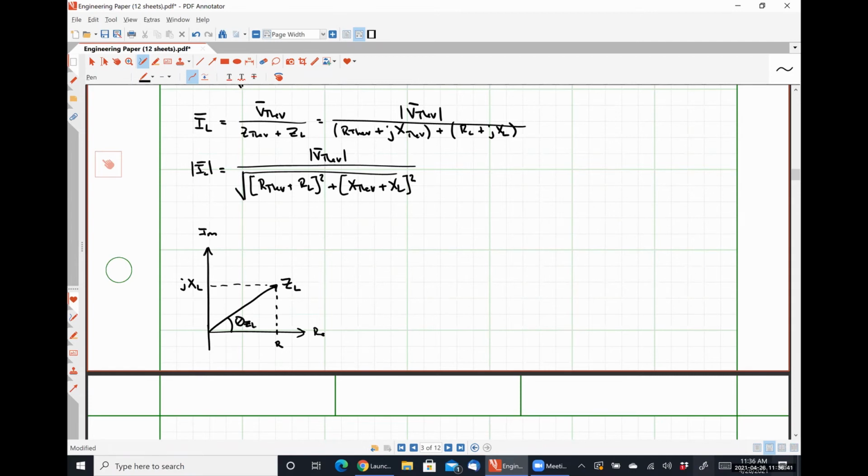Yeah. So if you recall, impedance by definition is phasor voltage divided by phasor current, which means we have Vm angle theta V divided by Im angle theta I, gives us a magnitude of Vm over Im with an angle of theta V minus theta I. So that theta ZL is the exact same thing as theta V minus theta I. So, recognizing that,